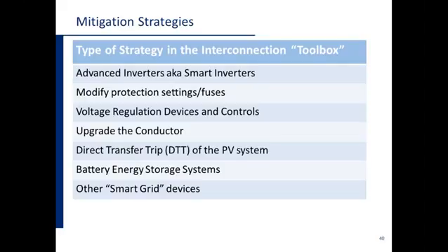And I'll go back to the smart inverter or advanced inverter technology. Pretty much all of the inverters being sold worldwide today have some of these smart inverter functions built in. So we know that those are available and fairly inexpensive, and it's just a matter of which functions to turn on and which ones to use to make the grid play better with the PV system.